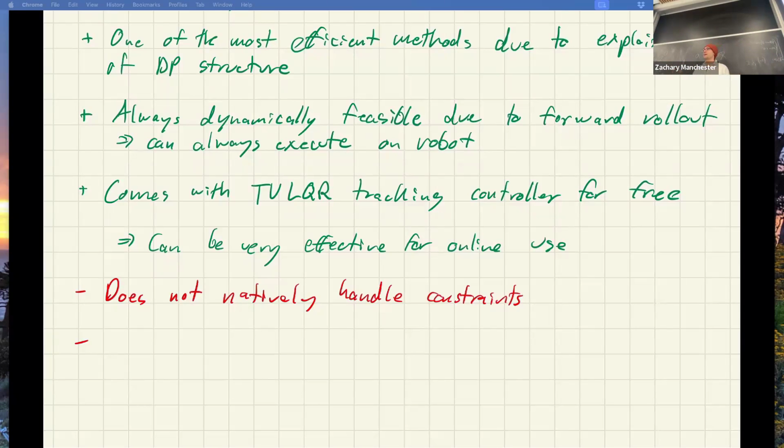It won't obey the dynamics because the RRT doesn't know anything about the dynamics. It's just sampling over poses or whatever, but you can throw it in and use that somehow to initialize a trajectory optimizer to get a dynamically feasible path right through the obstacles. That's a very common move. And unfortunately, these algorithms are not really well suited to that.